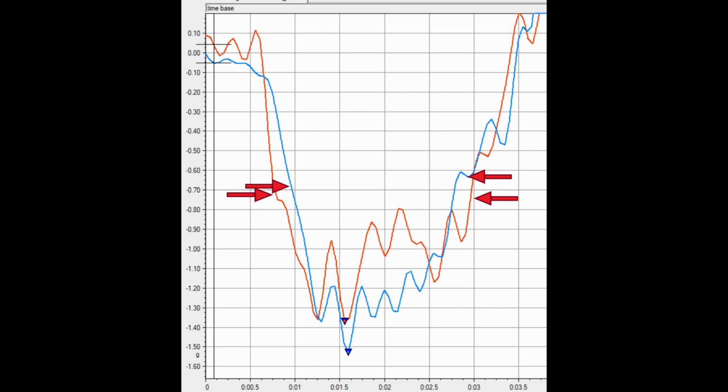And I can tell you from this test, we're testing basically jacking force. We increased jacking force and our lap times went down, although our peak lateral acceleration was less. And this was an autocross course, so a lot of direction changes, not a lot of time spent at peak lateral acceleration. So you have to ask yourself, for whatever track you're at, would you rather be at 1.5 Gs for 1 second or lower, 1.4 Gs for 1.2 seconds?